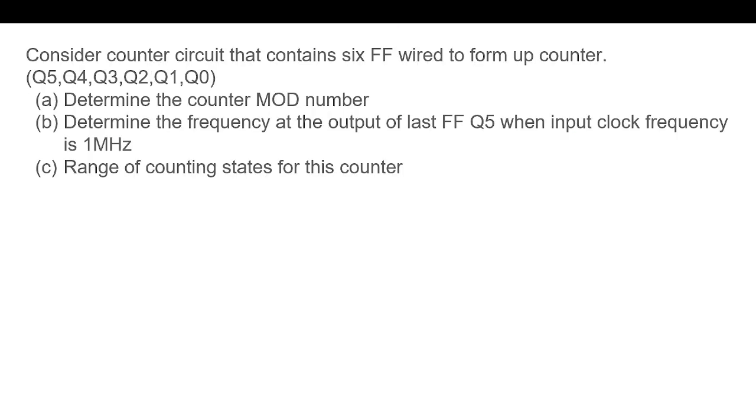So the next question: consider a counter circuit that contains 6 flip-flops wired to form an up counter. What will be the modulus of the counter? The modulus is 2 to the power 6, which is 64. So it's a mod 64 counter.